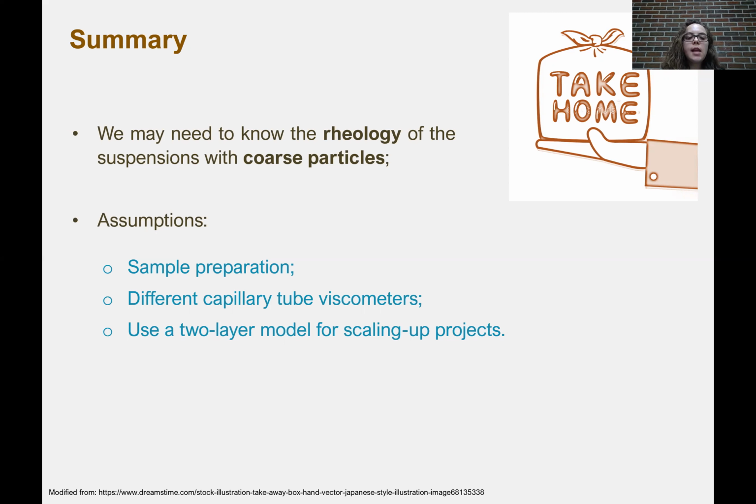Another limitation is that the authors consider the stratified solid layer static and the carrier fluid flowing on top of it. But we have to remember from the week 3 class that these capillary pipe tests are performed under laminar conditions. Would that be the case in a pipeline? How would we account for the turbulence effect on coarser particles? Would the coarse particles be part of the carrier fluid in a more turbulent environment?